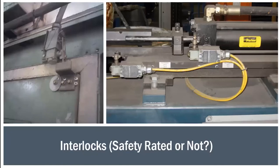Here's some other examples. As you look, are they safety related? All these ones aren't. It's another simple proximity switch. These are as well. This one on the left, it's hard to see, but there's actually a wire tying that one in place. And it's kind of interesting to see the contact points held in place by 7 fasteners. So the whole reliability of this particular interlock is questionable.